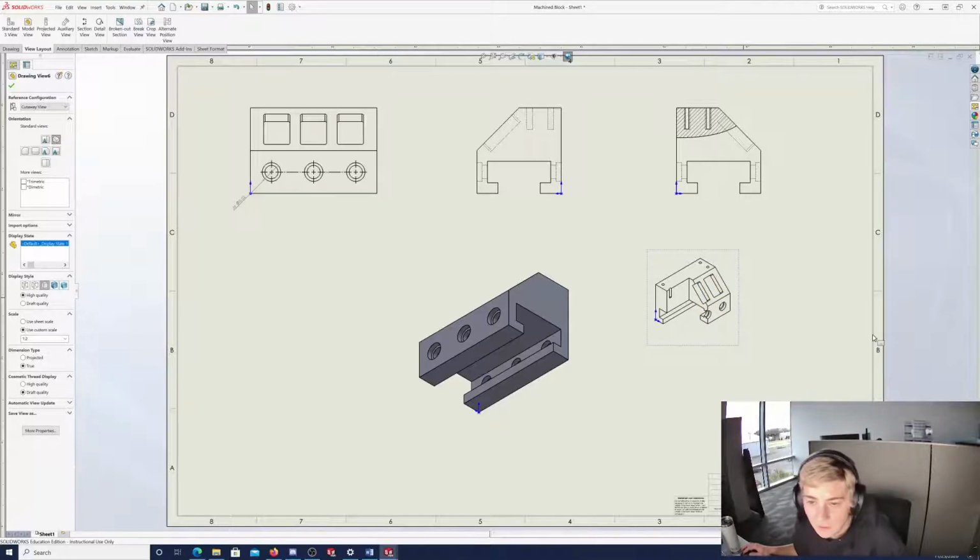It's added automatically, like up here, if you make the cutaway in the drawing. But when you make a cutaway view in your part and then you add it in, it doesn't automatically add it because the software doesn't know that you cut this away as a tool to make your drawing. You did it in the part, so it can't really differentiate, if that makes sense.